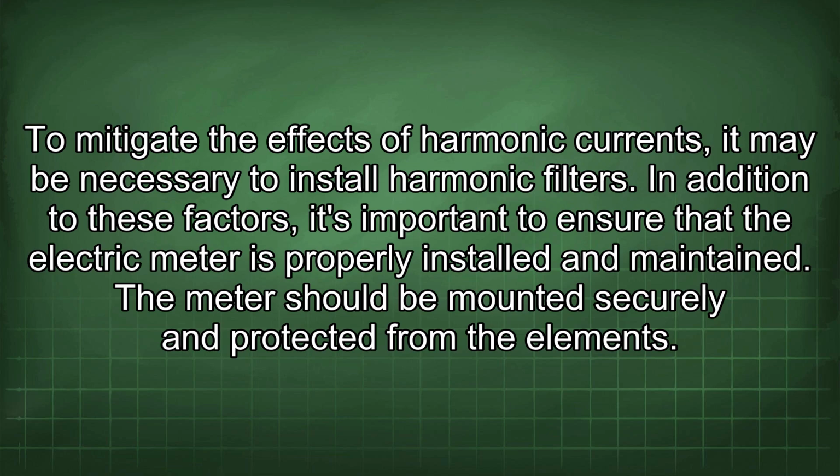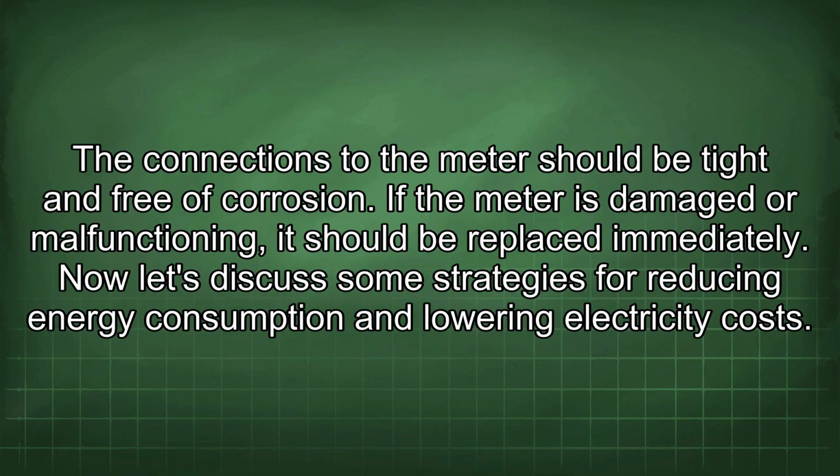In addition to these factors, it's important to ensure that the electric meter is properly installed and maintained. The meter should be mounted securely and protected from the elements. The connections to the meter should be tight and free of corrosion. If the meter is damaged or malfunctioning, it should be replaced immediately.